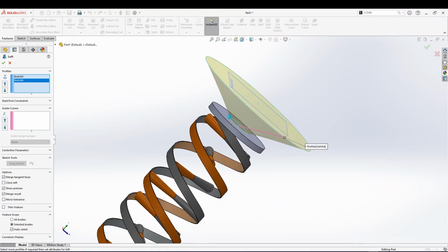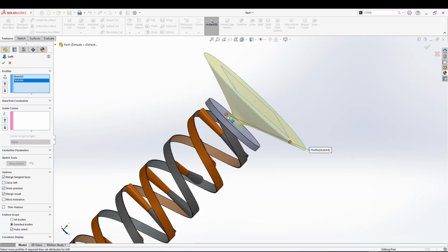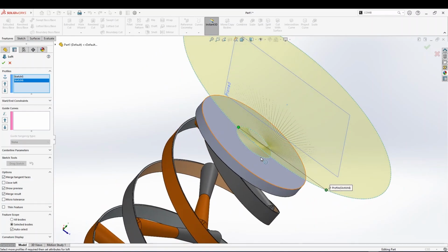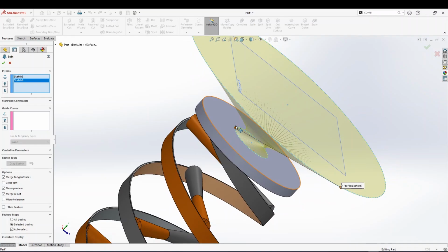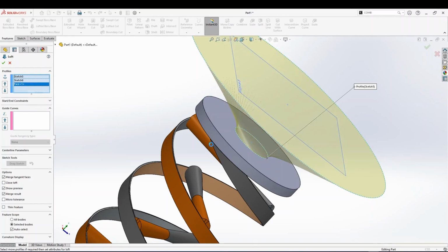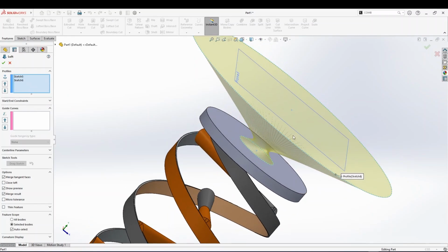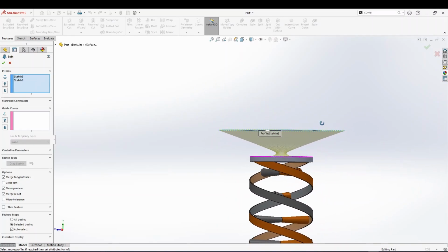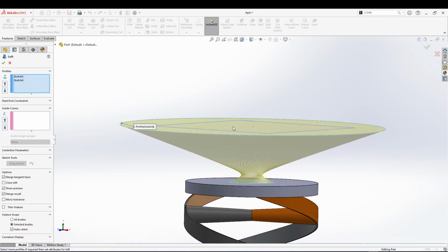And I want this connector to be moved a little bit here, so you can see what we have with the shape of our loft. I want this point to be not here, but on the almost opposite side of this one. As you can see, I just accidentally selected what I don't need to select. Okay, so it's here, and I think it's pretty good for us. It's pretty much the right form, that's what we wanted here. And again, I built this loft as a separate material, and I need to check that it is a separate solid body. And again, merge result.